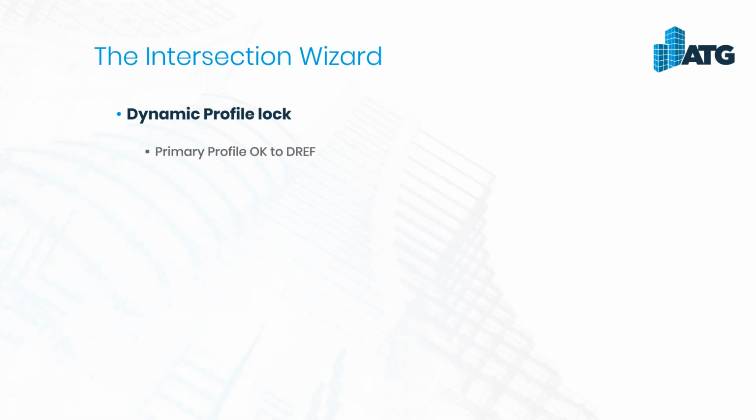Now, our primary profile, the roadway that we're not going to change, that one is okay to have a data reference. However, our secondary profile does need to live in our current drawing. Because it's going to now be dependent information, it needs to be able to update itself freely, and we can't do that through a data reference.